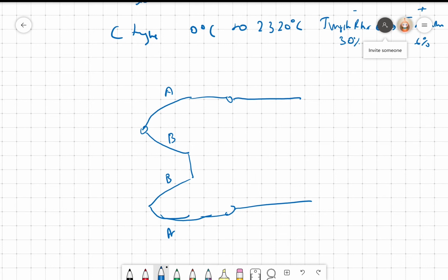We saw that the thermocouple wire is of different types, nickel chromium, constantan, and copper, iron. But normally the wires that we use are all copper, so we have to connect a junction. So let's assume this is iron constantan, this is Fe, and this is Fe, and this is copper, right?